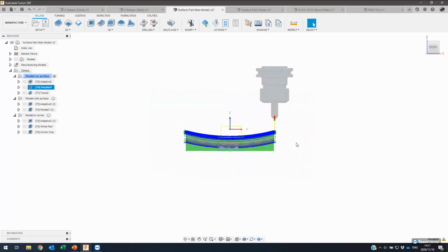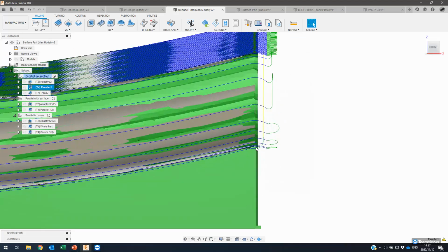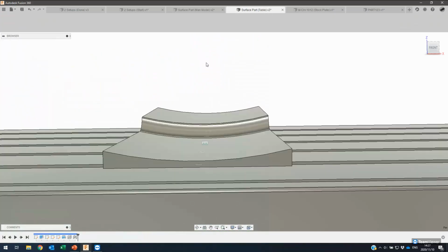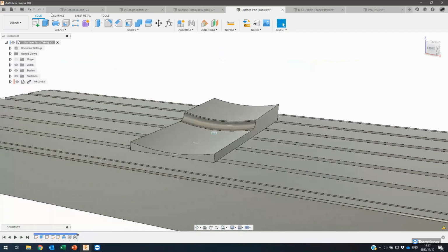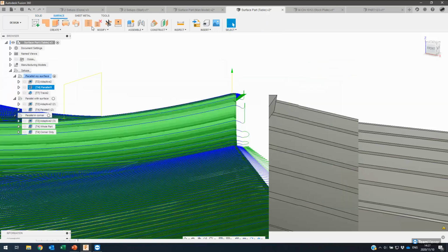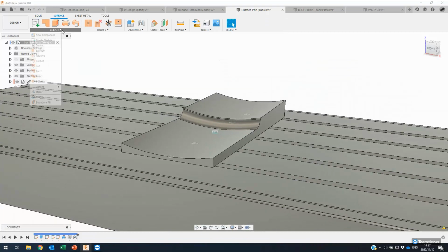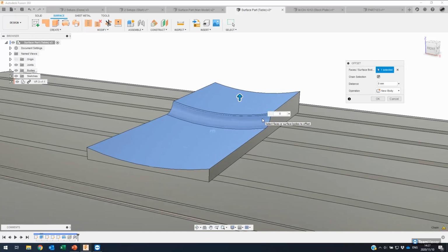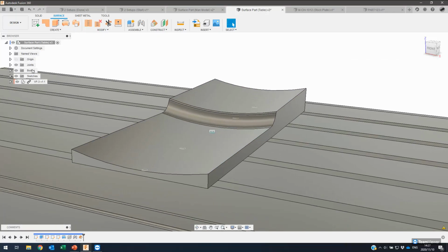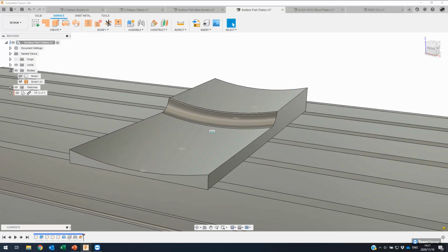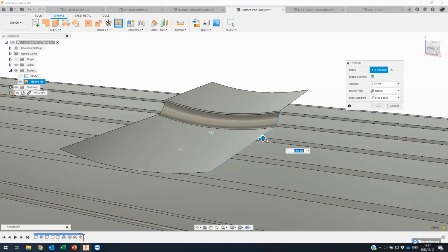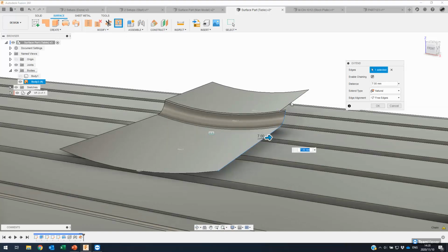Parallel surface there. We can look at that and see it tends to drop off the end there. We may want that toolpath to continue upwards. And so to do this, we would need to do, let's say, some surface modeling where we can create an offset from that face, so 0 degrees up, and then extend that edge outwards.